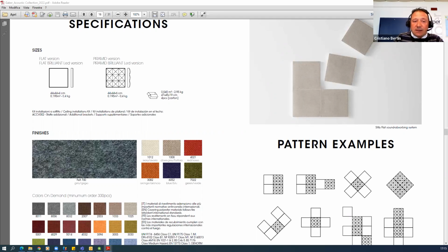To get a general improvement of the acoustic performance in an environment, it is necessary to use only a limited number of panels. The ratio between the required surface of acoustic panels and the available surface area is about 5%, exactly 5.08% of the total area of a room.